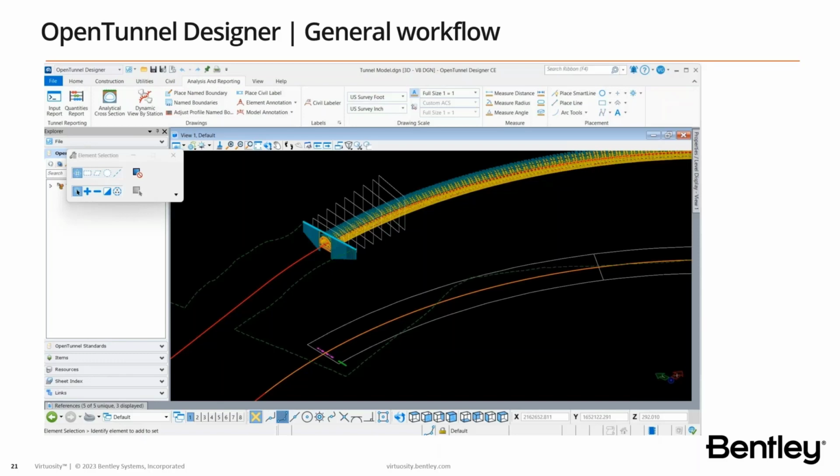But again, let's say you have your template drawn with another software solution in a 2D environment. It's just a matter of exporting that geometry to a DGN, and then you open a template on our side, and copy the geometry from your existing file into our file.